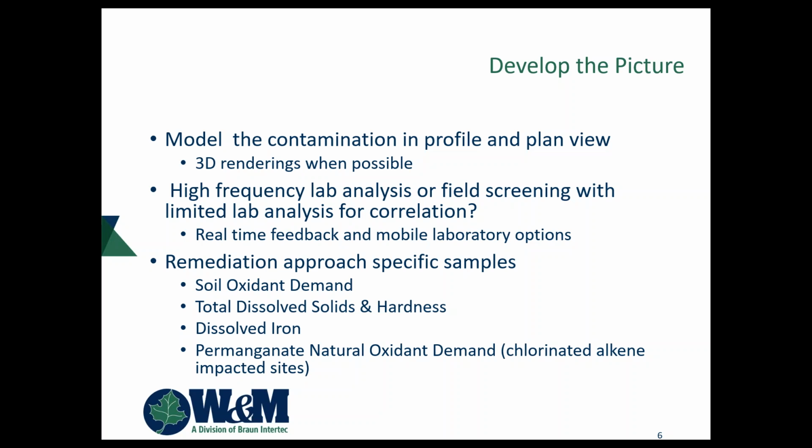If we're out there doing some soil and groundwater analysis for other stuff, let's grab an extra $40 sample or whatever it is for soil oxidant demand, just in case we might go toward an in situ chemical oxidation event. Even if it's a 10-15% chance that we'll go that route this early in the game, let's go ahead and grab it. We're already out there, so we save the mobilization cost.